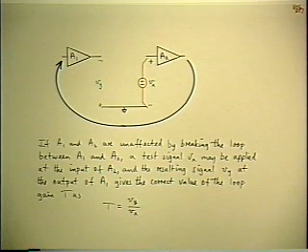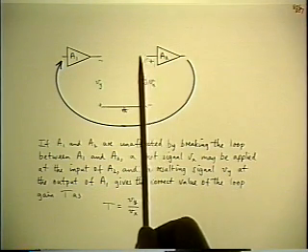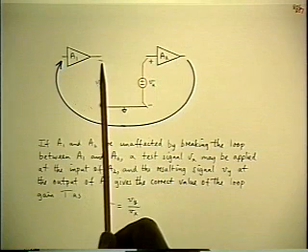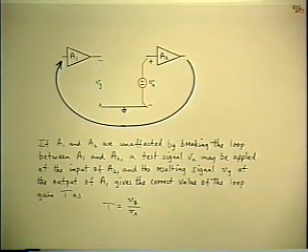One little point about this before we go on. Notice the choice of polarities. If I define Vx as positive, it will show up in the other direction at the other side of the break if the feedback is negative. And that's the case that we want to consider. Or qualitatively, in other words, if the voltage Vx goes up a little bit, the voltage Vy goes down a whole lot if the loop gain is large and negative. That polarity relationship is necessary to ensure negative feedback.